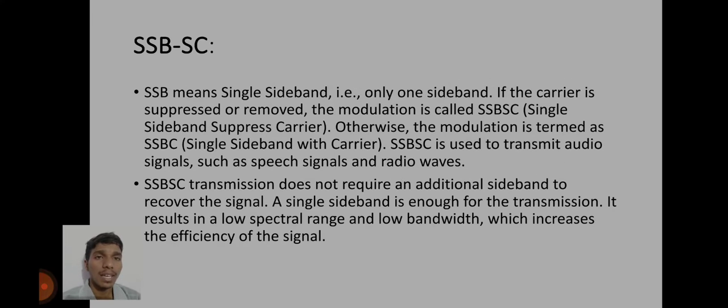SSBSC. The two sidebands in DSBSC are symmetrical and similar to each other, so we can transmit only one, that is either LSB or USB. So SSBSC, single sideband suppressed carrier.